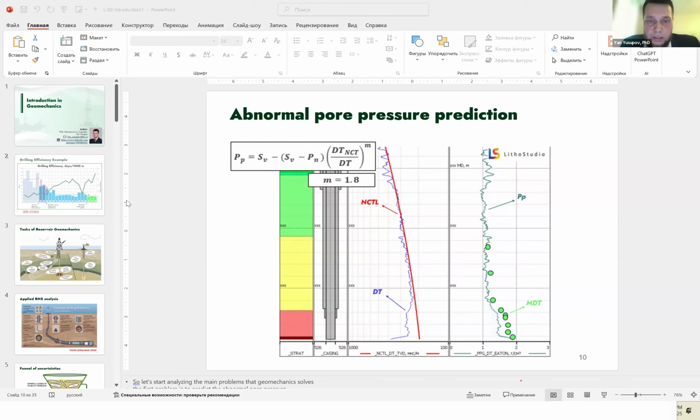How to choose when we can use Mohr-Coulomb criteria for some depth range, and use other failure criteria, Hoek-Brown, for deeper depths? Can you share experience using this criterion? The first method to understand which criterion you can use, Mohr-Coulomb or Hoek-Brown, is to build 2D charts, as you can see in the Zoback monograph. He showed charts where he built a correlation between sigma-3 and sigma-1 and estimated the configuration of points of failure and understood which criterion you need: Mohr-Coulomb, maybe Lade, maybe another.